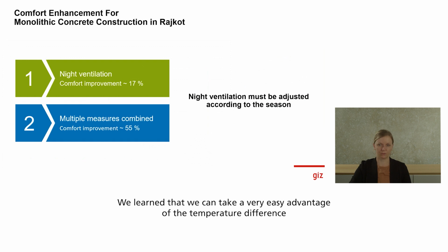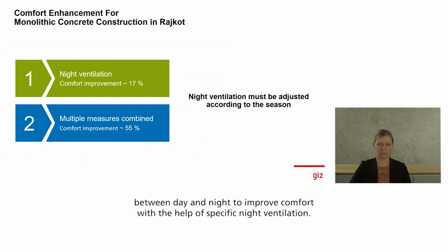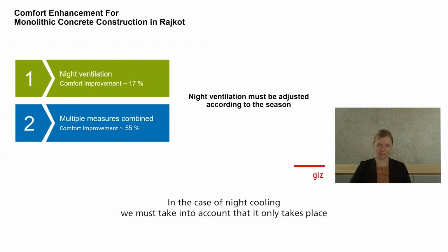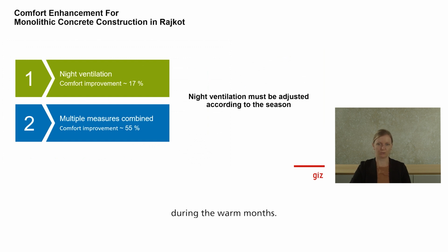We learned that we can take a very easy advantage of the temperature difference between day and night to improve comfort with the help of specific night ventilation. A combination of different measures, such as shading and night ventilation, was much more effective. In the case of night cooling, we must take into account that it only takes place during the warm months. In the cold months, the room would otherwise cool down too much.